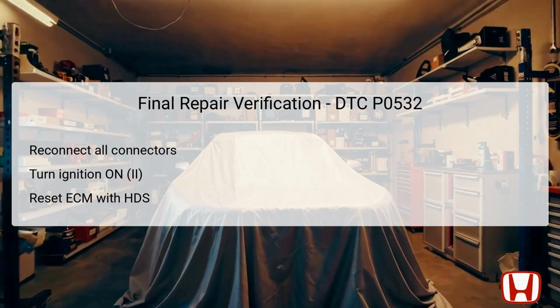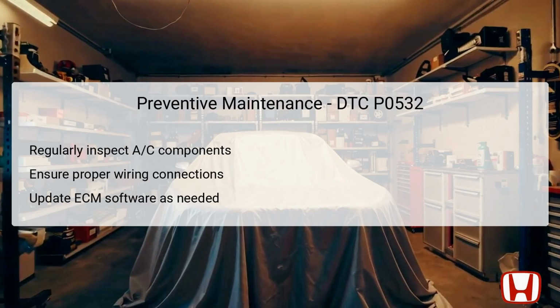Finally, it's imperative to perform a test by starting the engine, allowing it to idle, turning the blower and AC switches on, and checking for any recurring or new DTCs via the HDS to ensure that the issue has been resolved successfully. Preventive maintenance is critical in ensuring ongoing functionality of the AC system and preempting issues associated with DTC P0532.